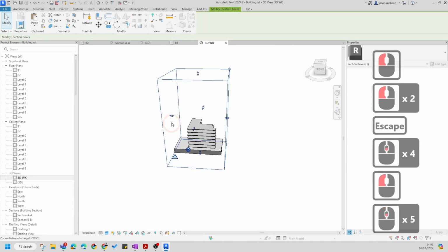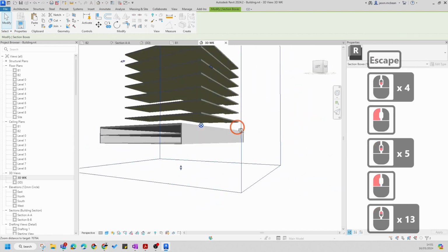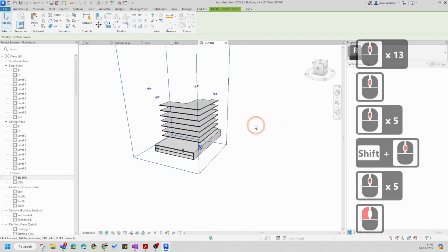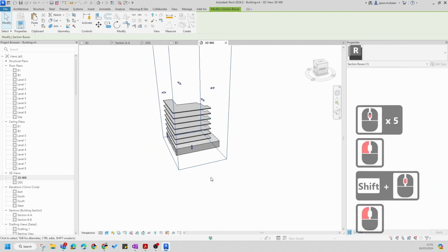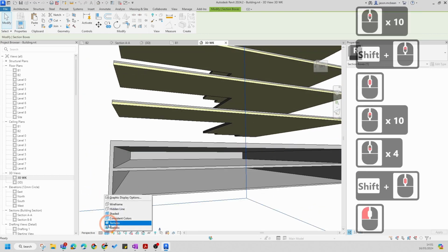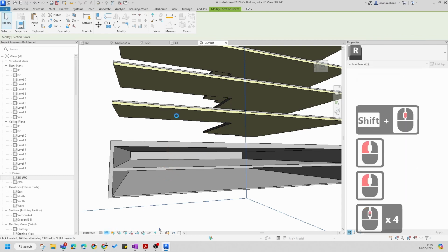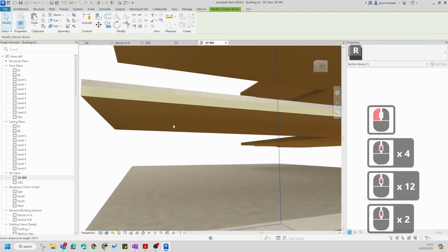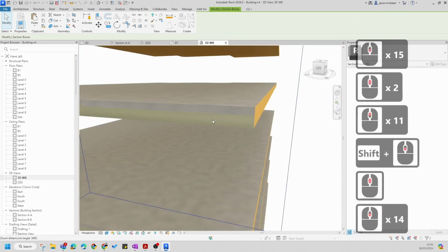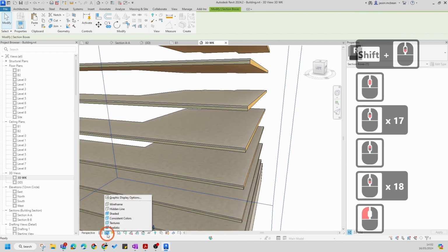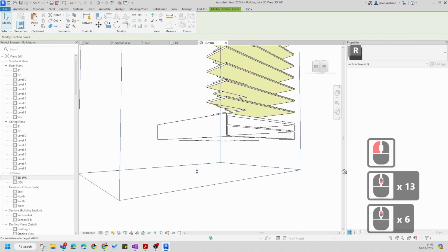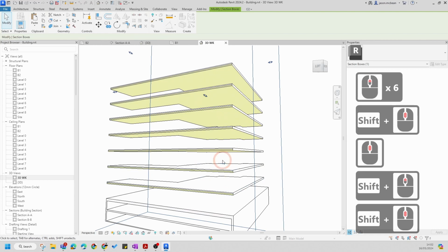So now if I use the section box quickly, I can use this view quite rapidly to kind of see how I'm working. Okay, so this is actually quite neat because I think a lot of you are still battling, you're just seeing too much information, it gets a bit overwhelming. But now if I go and look in 3D view, and I change this information to realistic even, you'll start getting the real materials, so you'll actually start seeing this information in quite a lot of detail now. Okay, because you can see how the floor slabs are set up correctly, etc. Okay, back to hidden. So now I'm starting to get a good idea of how this information is coming together.